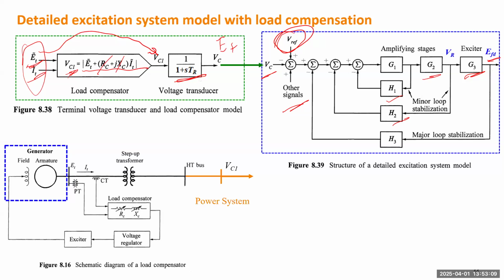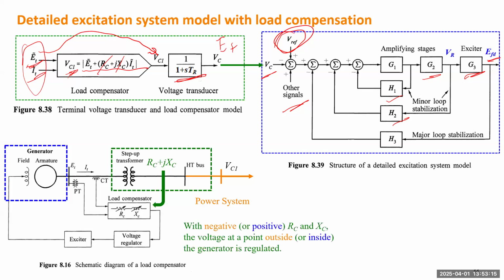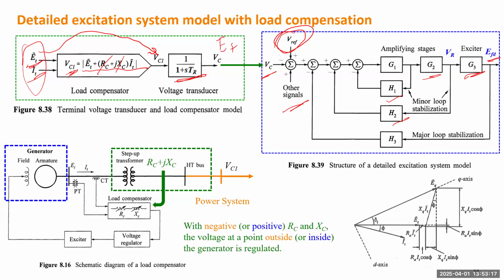Yeah, we can. So this is just detail, but let's talk about the same story. If you don't look at the answer, just use this phasor diagram. This phasor diagram is describing how you get terminal voltage from the internal EMF EQ. So the EQ is much longer than ET, right? For this case, this is terminal current IT, and ET is terminal voltage. That's the same IT, ET there.